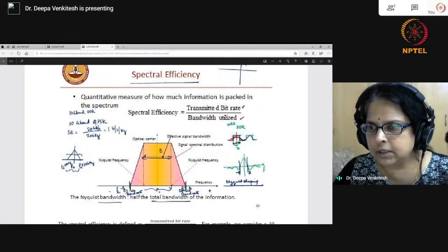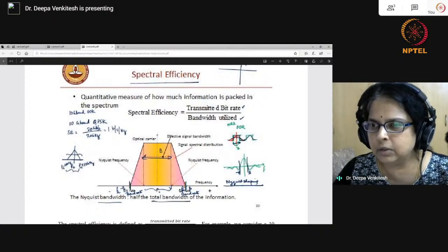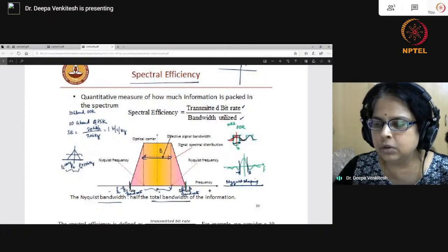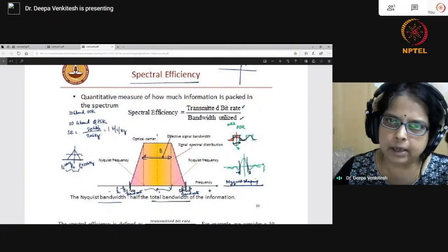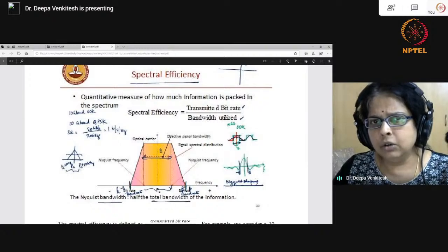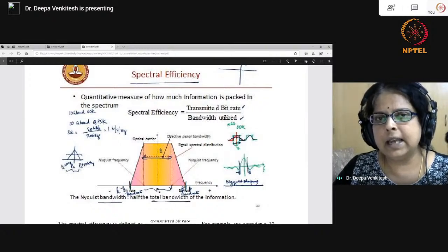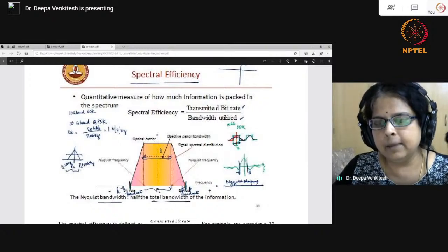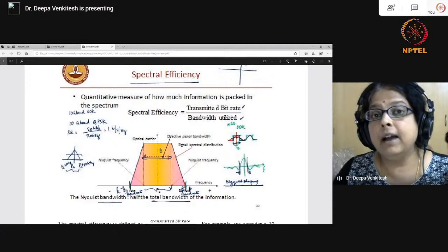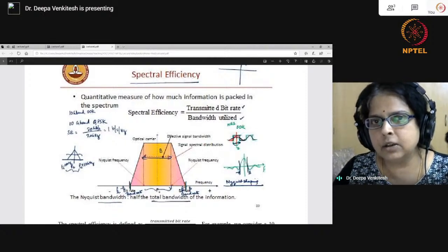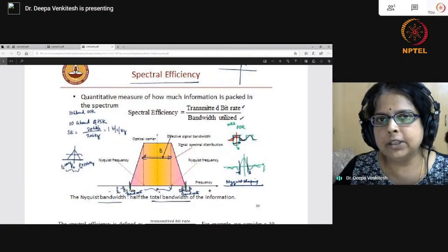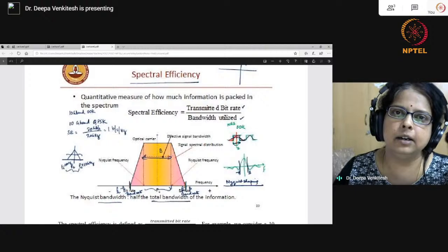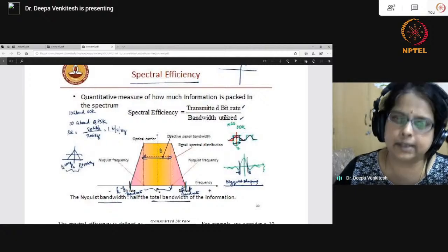Monojit, is it possible to send electricity transmission through optical fiber cable? So this was answered to you on email also. No, it is not possible to send electricity through optical fiber cable. Although what we have is, in electrical cables, current carrying cables, we have optical fiber embedded. So these are called OPGW cables, which are essentially the ground conductors in power transmission lines.